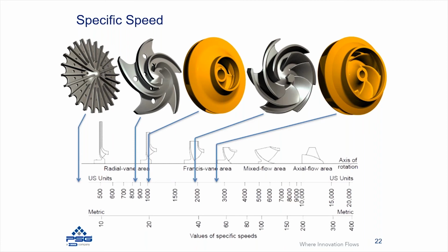On the far left here, you have what would be a traditional ASME B73.1 low flow impeller, and this impeller is a complete radial design. It's going to generate very high head pressures and very low flow rates, and you can tell that by the impeller design. Then as you start moving towards the left, you can see that the vane profile starts getting wider or taller, and the flow begins to be less radial and more axial in nature, and the specific speed begins to increase.